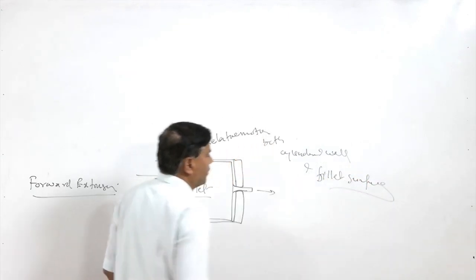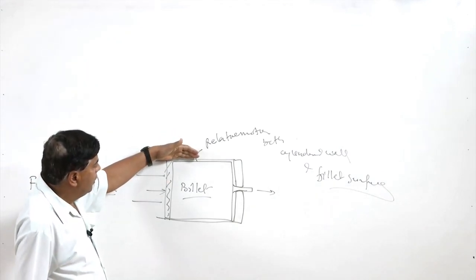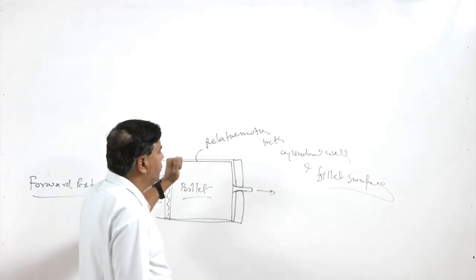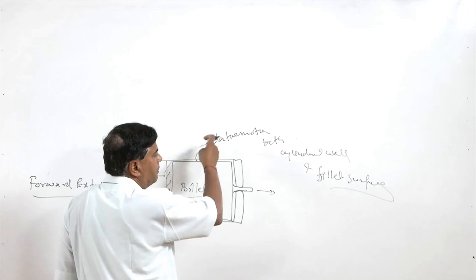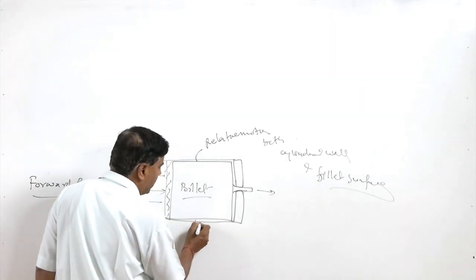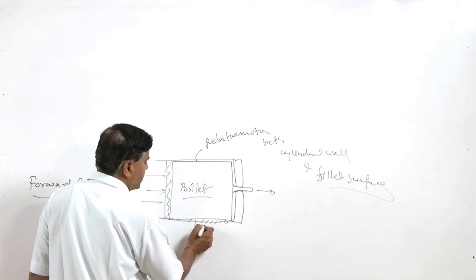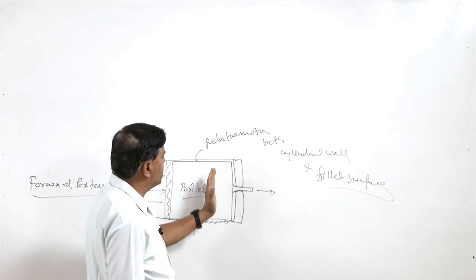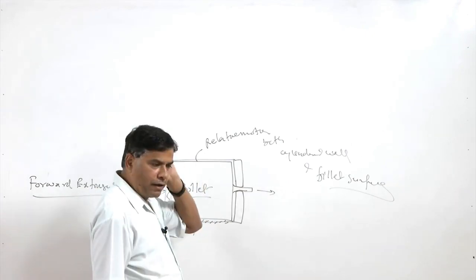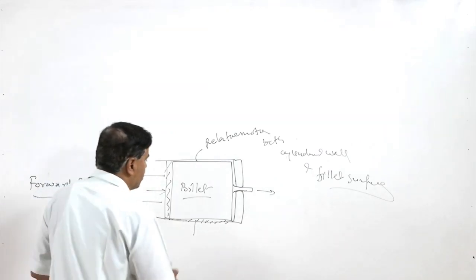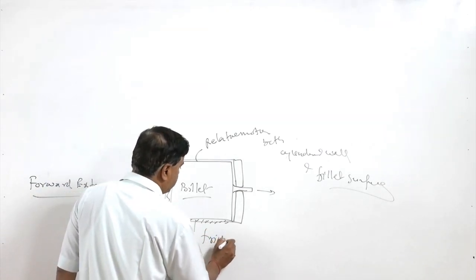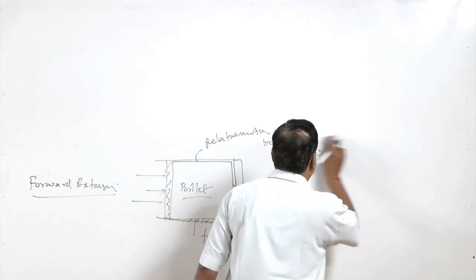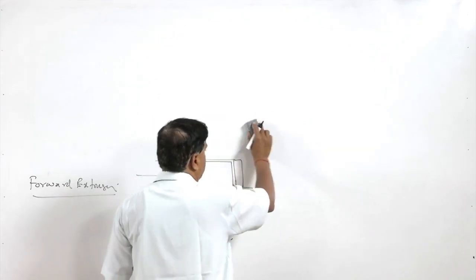This causes a lot of friction. The wall of the cylinder and the billet have relative movement with each other, and at high temperature a lot of frictional forces are present, which makes the movement of the billet material difficult, or needs more force from the ram. This friction is one of the negative aspects of this process, and it increases the energy or force required for extrusion.